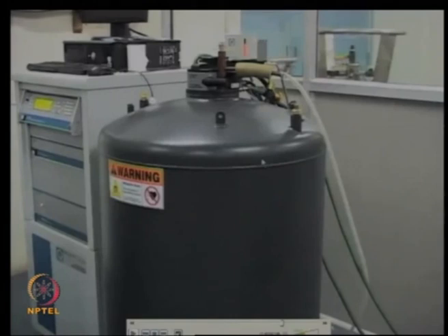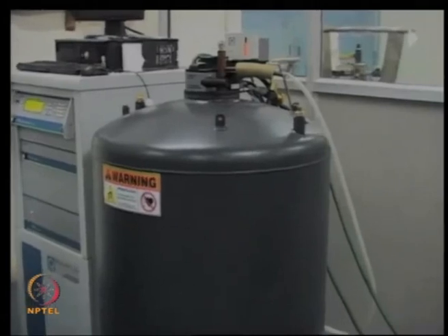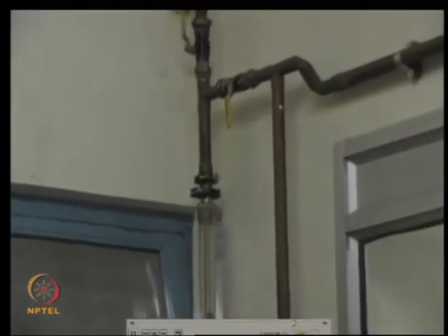Whatever helium is delivered, all that helium gas has to be recovered. We should have a recovery ratio of above 98%. That means we should not lose any of the helium that has been delivered in the liquid form. Okay. So, this is a user community who is now nearer to the liquid helium production, and you can see again that the helium gas will go to the recovery connection later.